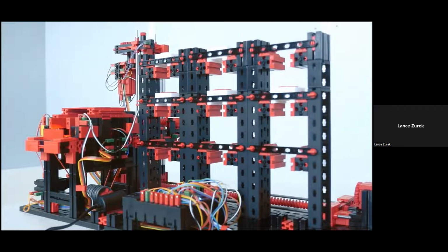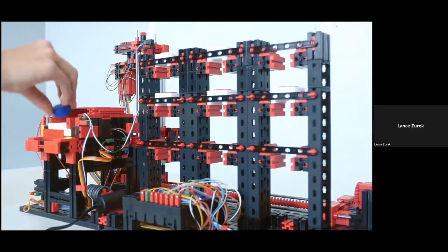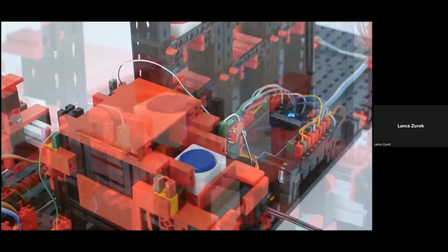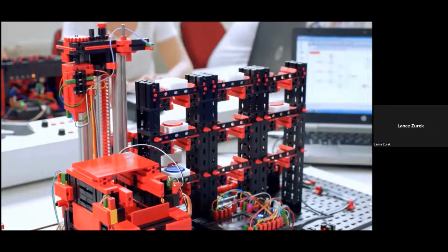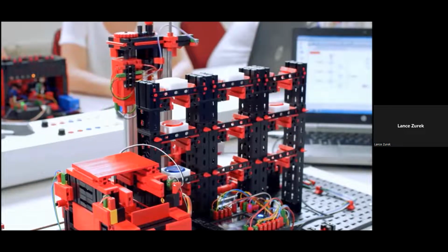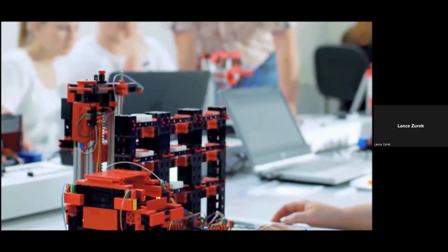The dimensions on the model are approximately 19 by 28.5 by 15 inches, and it has a weight of just around 18 pounds. Again, the 24-volt version has a relay board for motor polarity reversal and both a multi-pin connector, again 34 pins with a grid of 2.54 millimeters, as well as additional PCB terminals with push-in connections for all inputs and outputs. Again, you will need to provide your own PLC and programming.